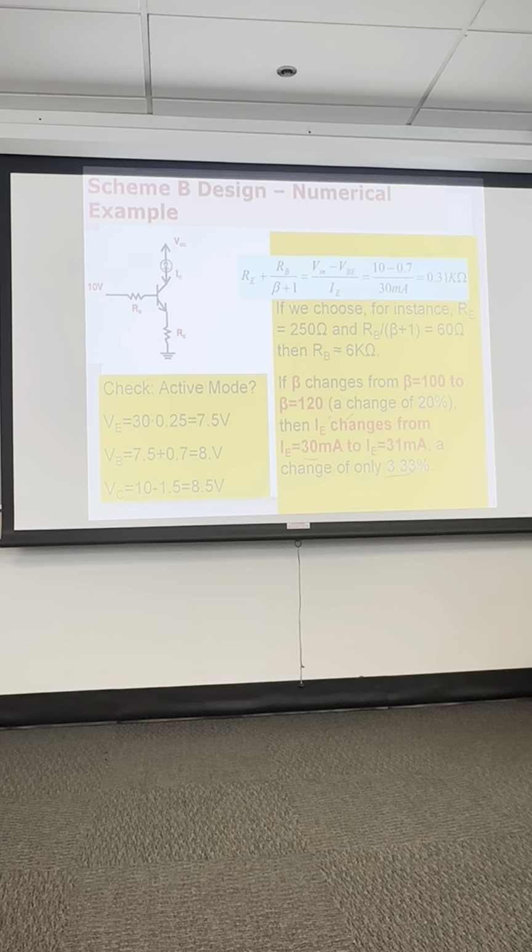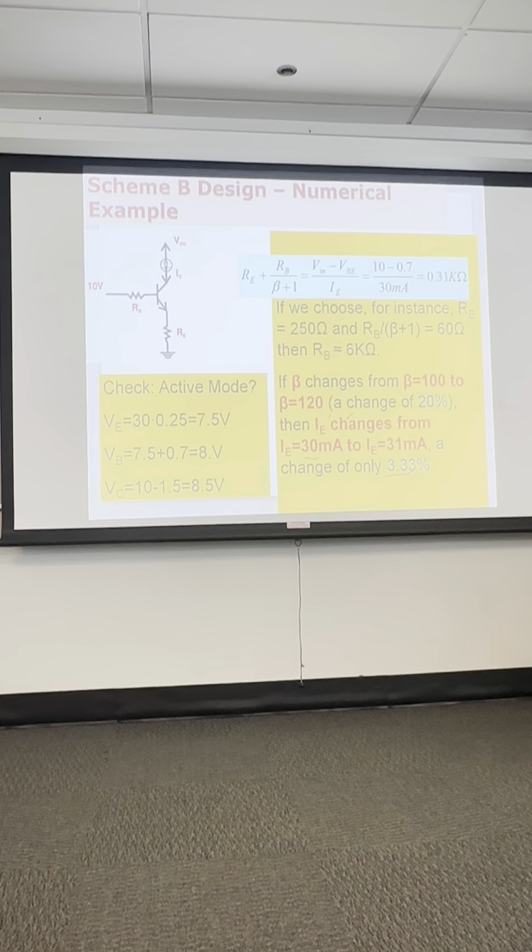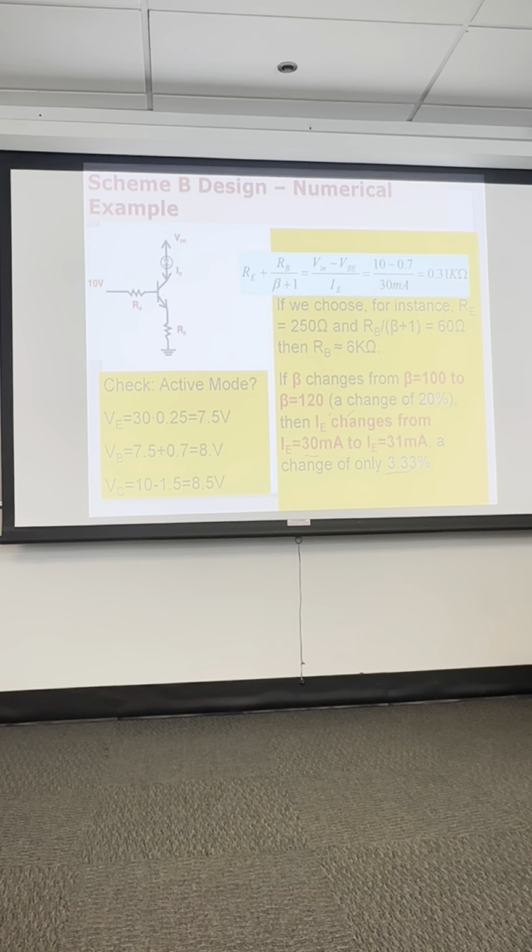Now, if you're the engineer responsible for making hundreds of these circuits, you would probably visit the foundry. You need a plane trip probably over to where the foundry is at, and you would get to the manufacturing engineers that make these transistors, and then you would start going over the statistics data to get a better idea of what's going to happen with beta: worst case beta, then nominal, and then best case beta.